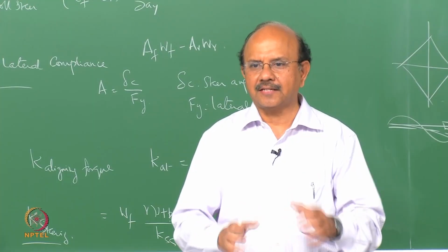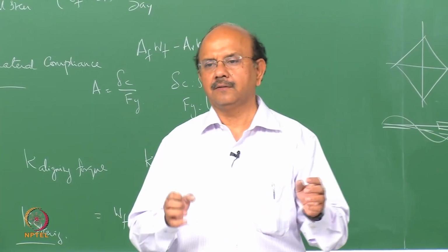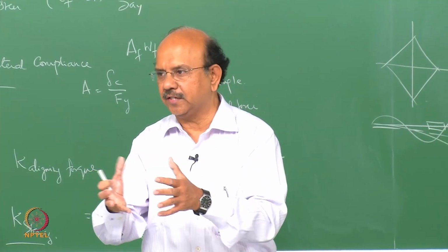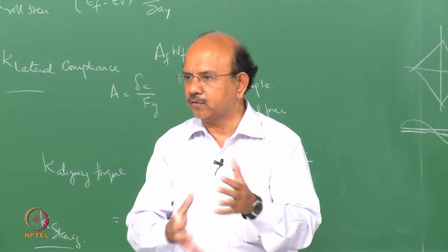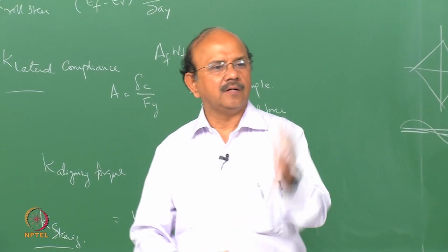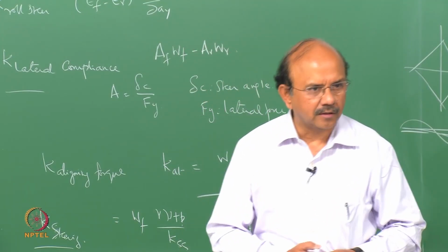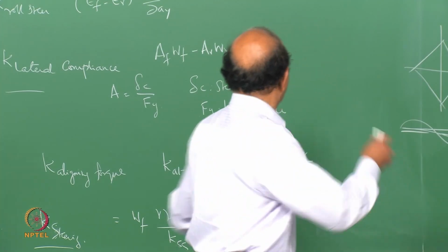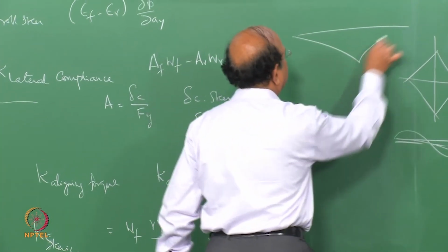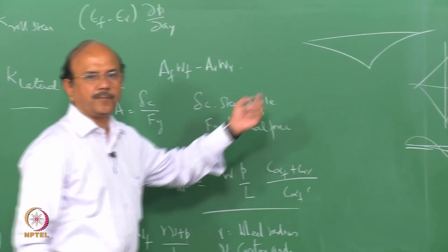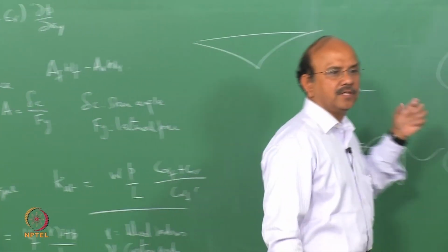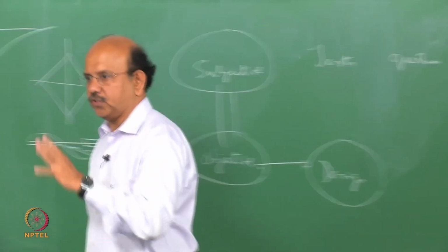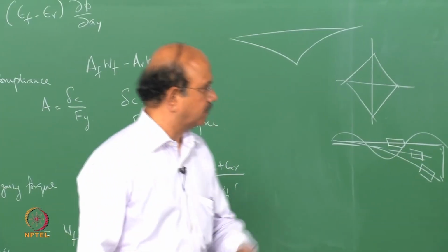Then I will take the car and accelerate, loosely hold the steering, and see whether it is going to one side because of torque steer. It is steering on its own because of this acceleration that I am giving and because of the torque that is available at the wheel, right. When I decelerate, is it coming back? In other words, is the car having a path like that? First part is acceleration, second part is deceleration. So this is what is called torque steer. That's the next thing I will check, or you will check.